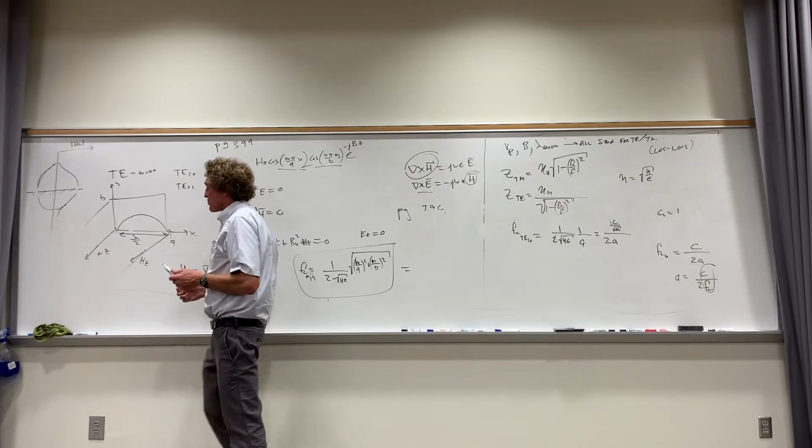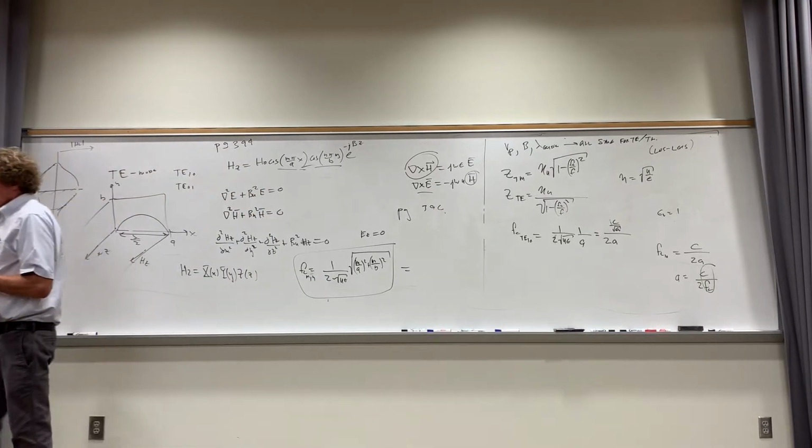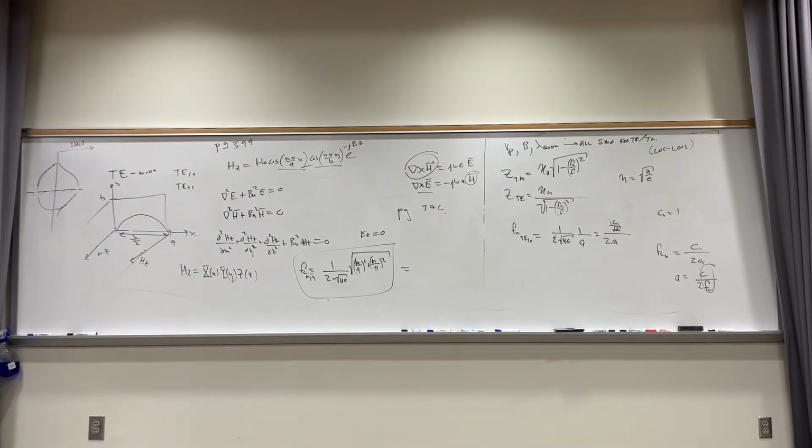Now here's the trick with propagation. Dr. Wentworth's book will say to calculate all the modes of propagation up to like 3.5 gigahertz for certain dimensions. And you'll get the 01, the 10 mode, then possibly the 20, then the 11, and then the 21 mode, and you'll have a bunch of different possible modes up to there. You only want one mode propagating within the waveguide.